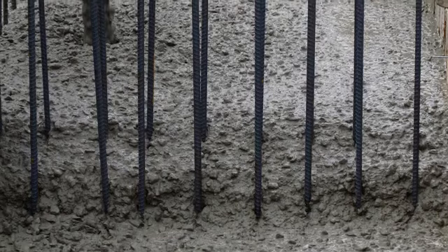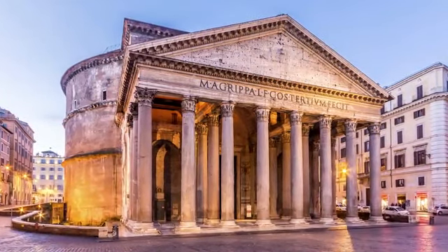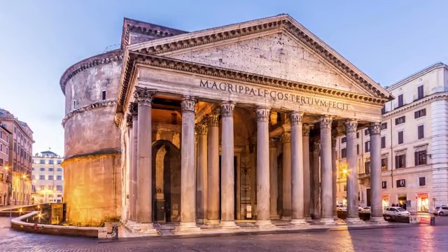Pictures taken by David Billington many years ago clearly show the cracks in locations below 52 degrees. I visited recently, and although the cracks aren't as clear as they were many years ago, they are still there if you look for them. Concrete vaults today have steel bars embedded in the concrete to enable the structure to carry a mild amount of tension. This is called reinforced concrete design, that is, concrete reinforced with steel. The Pantheon does not have steel reinforcement, so it can be assumed that these cracks were there from the beginning.